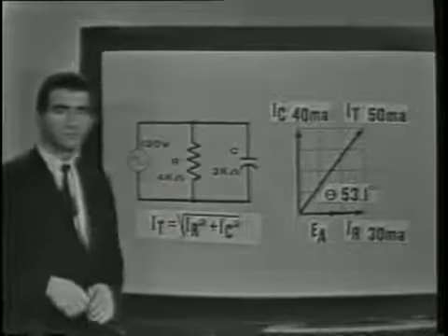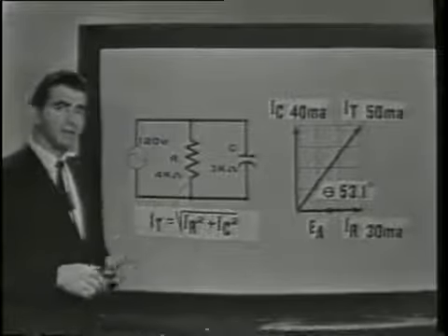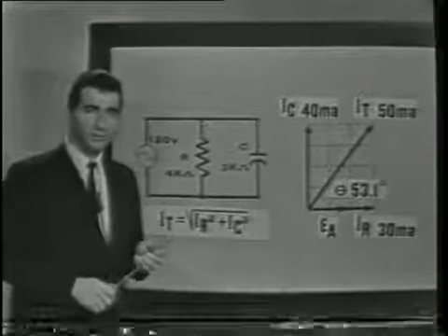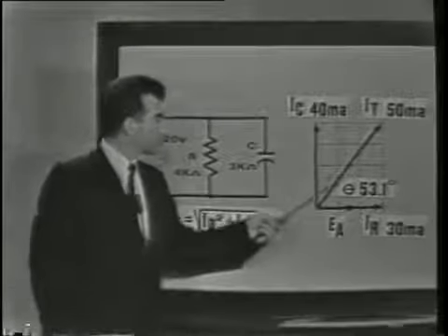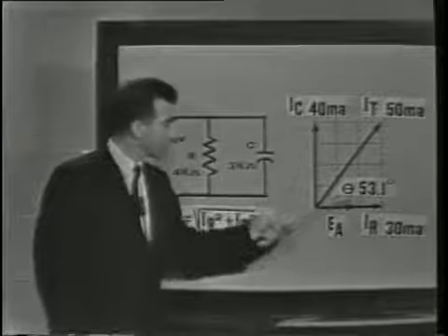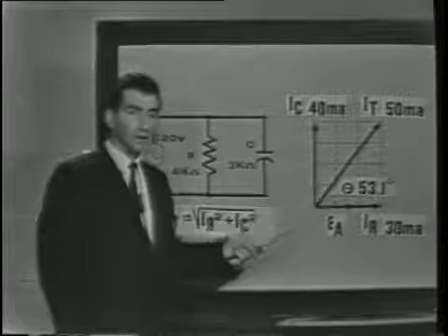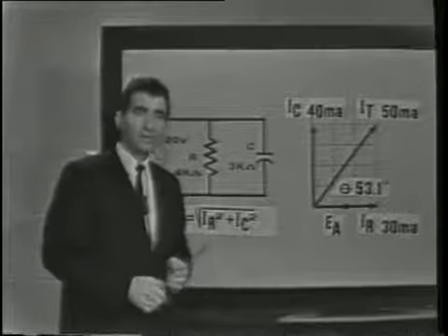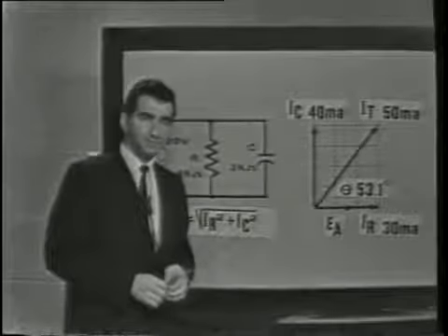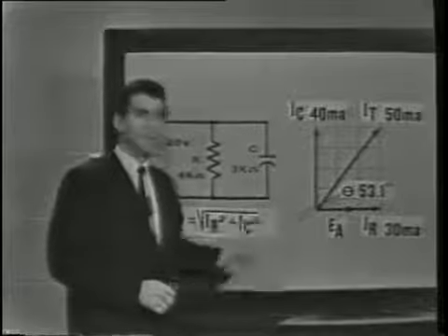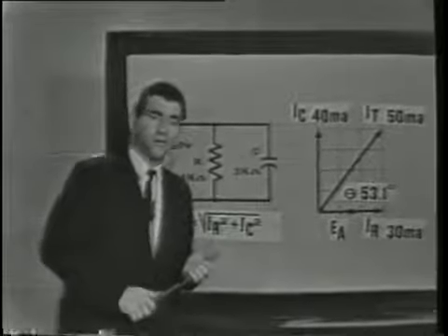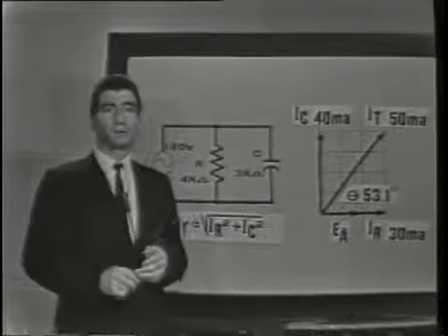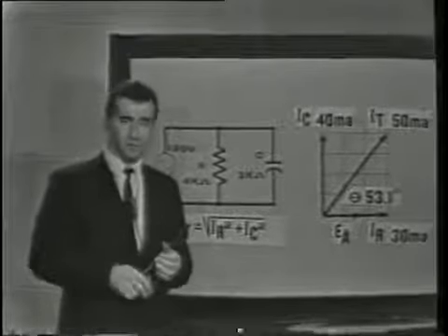Pythagorean theorem. Total impedance in the circuit was found by using Ohm's law also. And the phase angle can be determined, once again, by simply measuring the graph, or, more exactly, by calculating the sine or cosine of angle theta, or the tangent, and using the trig tables. The phase angle is important to us because it gives us an indication of the power factor, which we defined as the ratio of true power to apparent power.